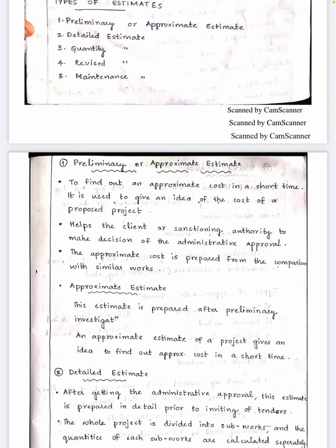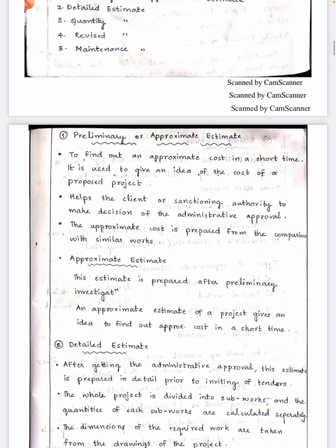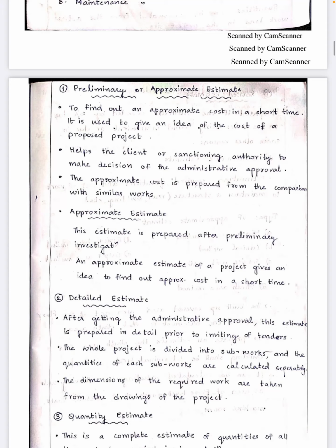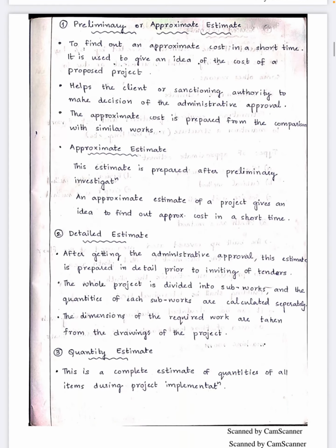The approximate estimate is prepared from comparison with similar works. It can also be used for comparison purposes. The approximate estimate is prepared for the preliminary investigations. The approximate estimate of the project gives an idea and finds out the approximate cost in a short time.